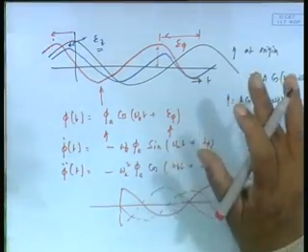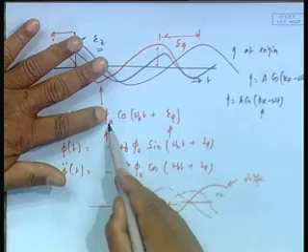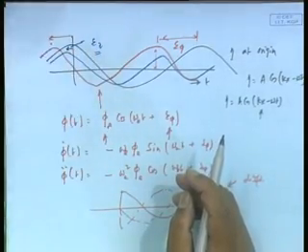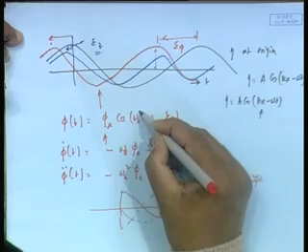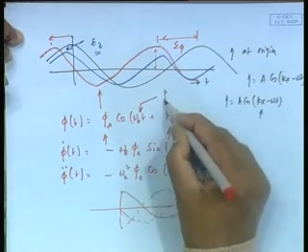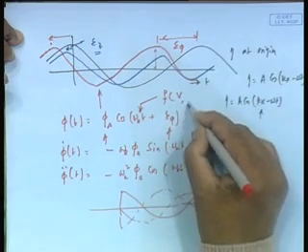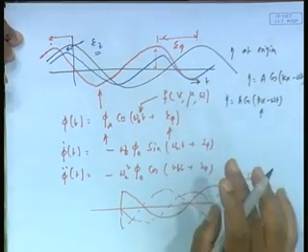So my point is that if I know this and I know this, I would know everything I need to know as far as roll motion, or a particular single degree of motion, is concerned in that single wave. Remember, omega e is a function of what all things? Ship speed v, heading mu, and of course wave frequency omega.